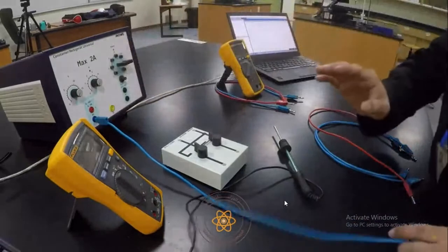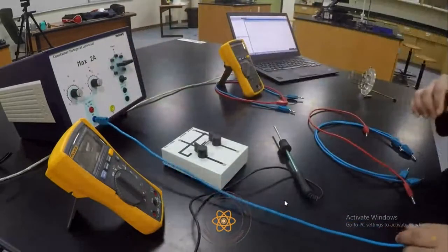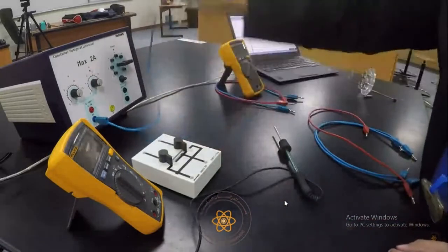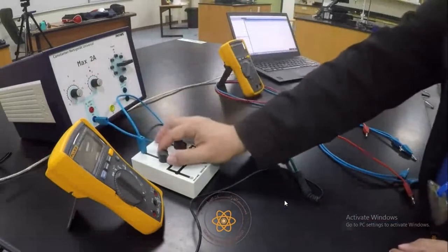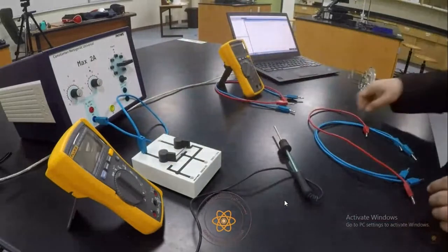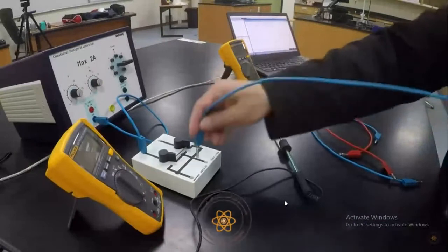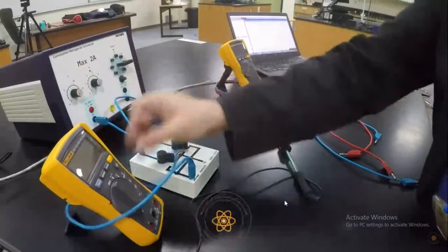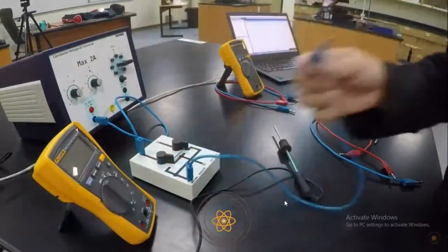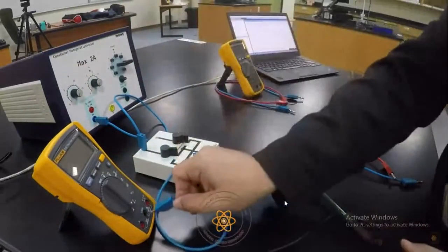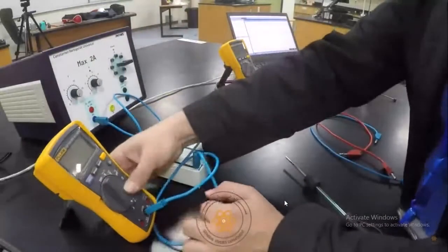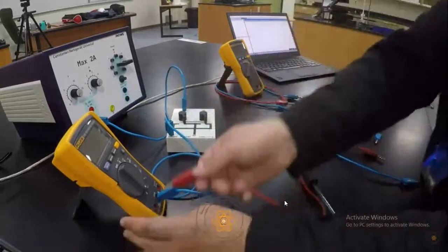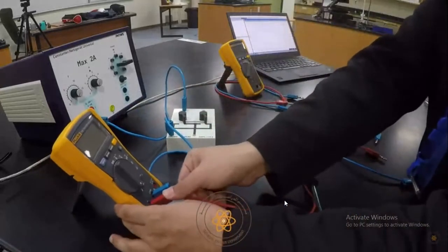Now make sure that your power supply is off and the voltage and current dials are set to 0 for safety. From the power supply, we connect to our switch. Again, make sure that your switch is off. And then from the switch, we connect to our digital meter. Because we started from the negative of the power supply, we are connecting the cable to the common terminal of our digital meter. Next, from the common terminal, we will go to the ampere terminal, A.